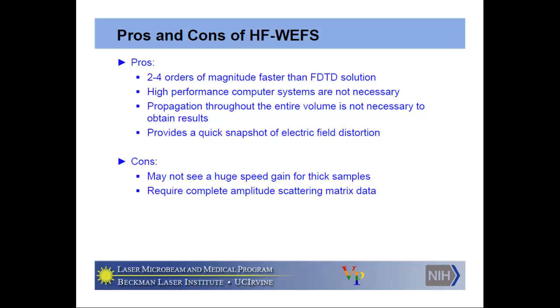And also you can reduce the detector resolution, so you can place grid locations at different spacing, and you can get a quick snapshot of the electric field distortion. Then if you need detail, you can increase the detector resolution, and so you can see more details.